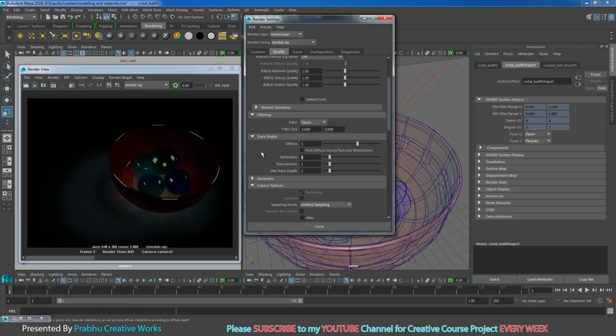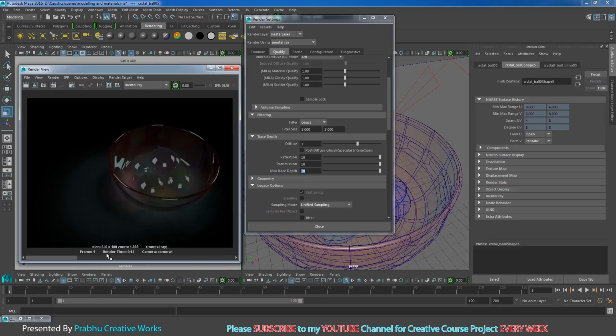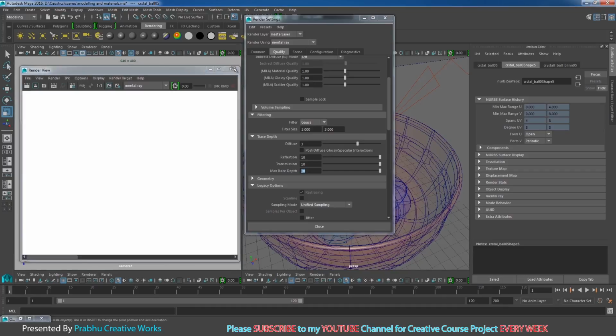So I will give at least 10 reflection and 10 transmission. This one is the sum of the two, so I will give 20. I will keep this image for comparison and click render again. Now you see our crystal cup and crystal balls are shown very clean. This is what we expect, but I want to reduce some reflection for these objects.